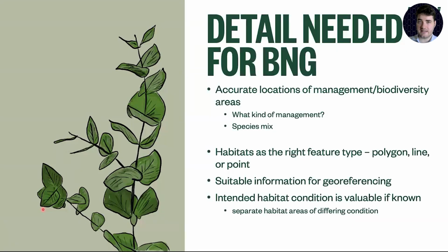And if you're not georeferencing the site, it would be really beneficial to have good georeferencing information nearby. Obviously, plans are not always drawn to scale, so that can be challenging. But I've regularly georeferenced CAD designs using the external building layout outside the red line boundary to work out where exactly this thing is supposed to lie. And that's not an unusual process. So if you do have good measurements and good information about that, it can be useful for understanding where you have drawn the red line boundary and where you think the boundary of the site is, because frequently there are differences between red line boundaries that people submit and, say, the Ordnance Survey assessment of where that land is.